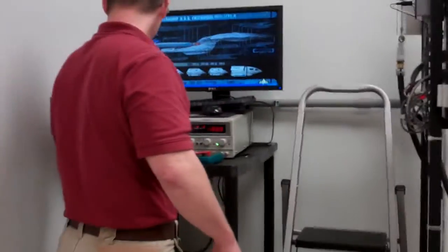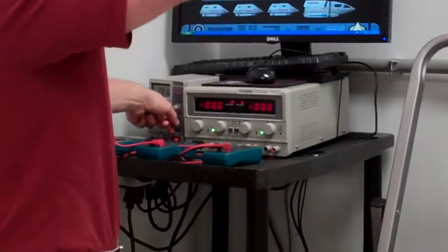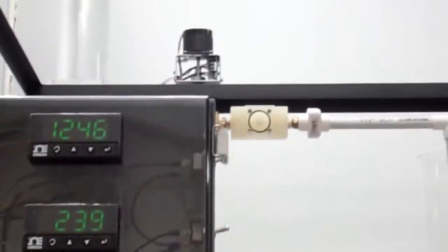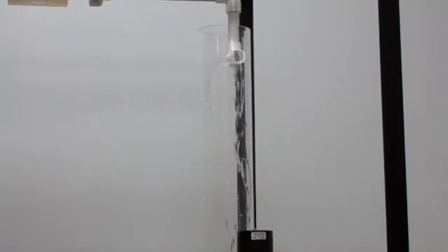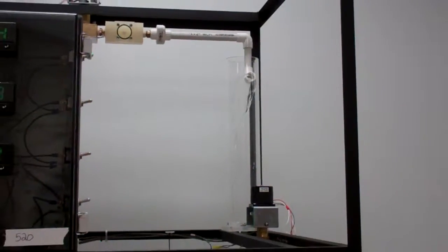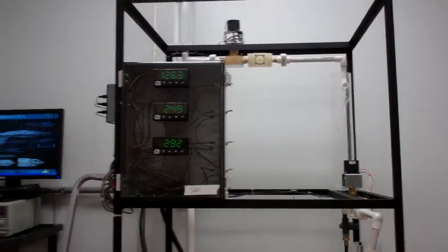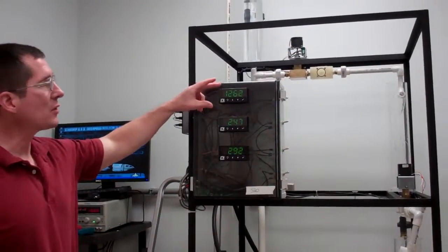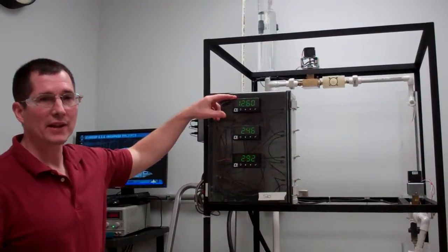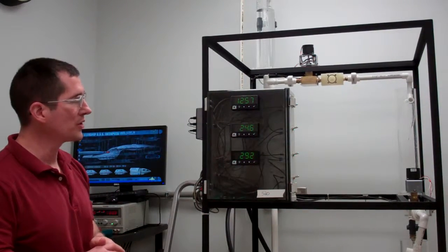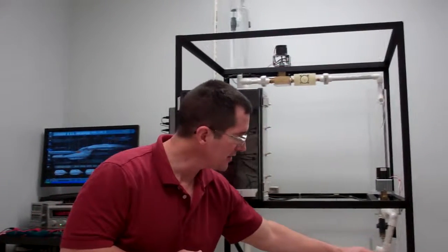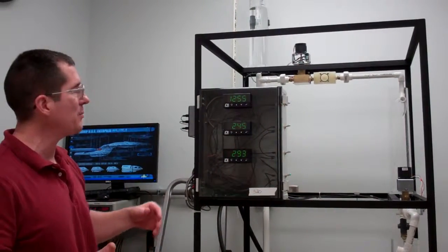I'm going to go ahead and open up my control valve. And as you can see, the valve's now starting to open, and we have some flow now going into the second tank. So here's the interesting bit. For level control, you have to have a set point level, okay? Some set point that you want to control, keep the tank at that specific level. That's called the set point.